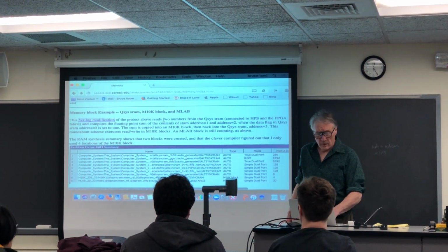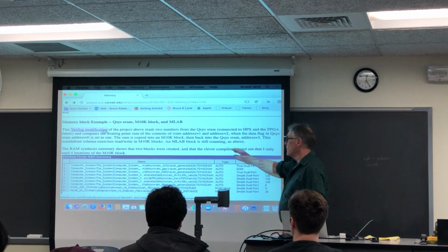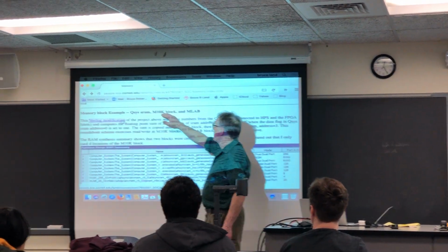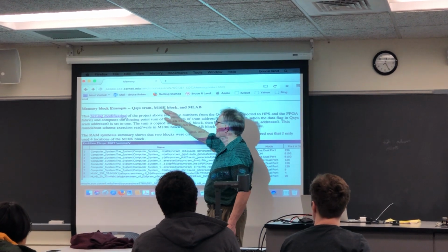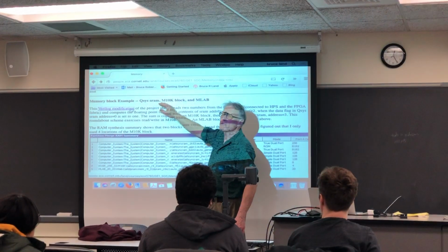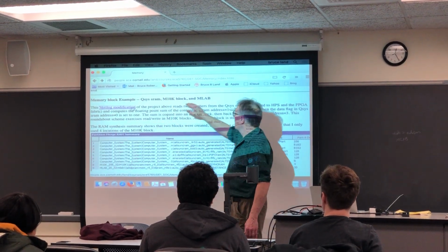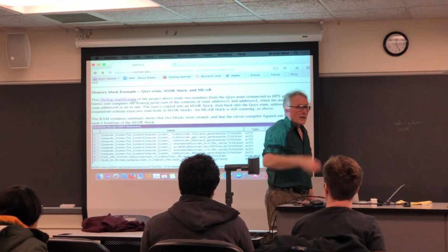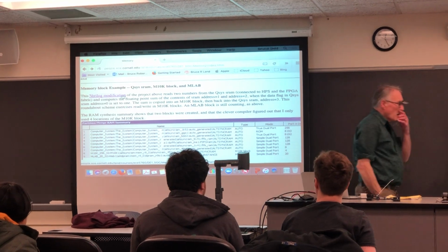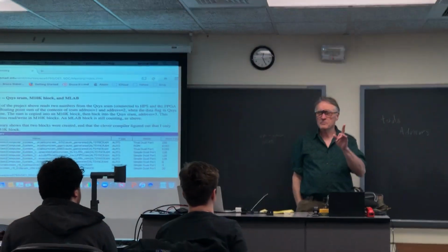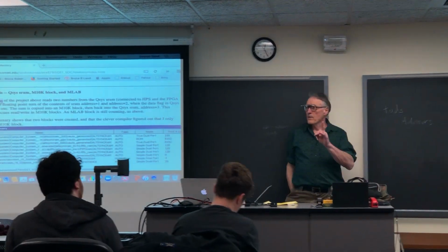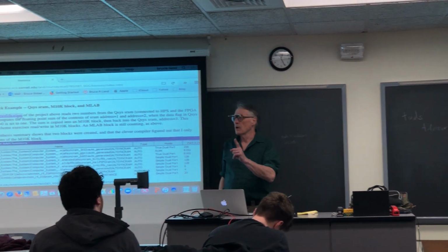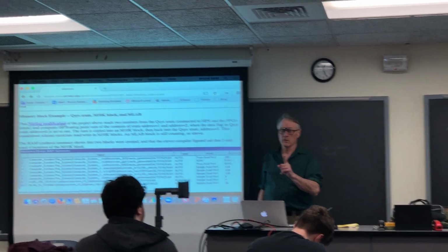So again, examples of how to use static RAM M10K, QSys static RAM M10K blocks, which are really the same, they're just instantiated differently. And MLab blocks are all here. MLab and M10K blocks are all single access blocks. You get to do one operation per port on each clock cycle.